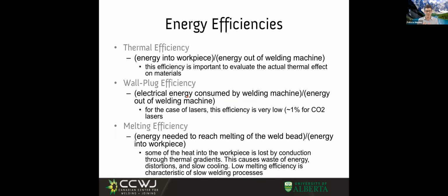Energy efficiency. I want to talk about two energy efficiencies. I have a bullet for 3 here. I'm going to touch on melting efficiency only briefly. Thermal efficiency is how much energy went into the workpiece versus how much energy came out of the welding machine. The main difference is how much was radiated out, right? That in the light of the arc.